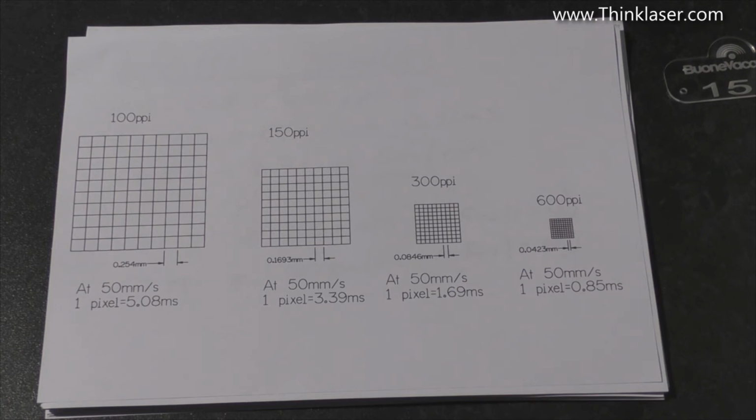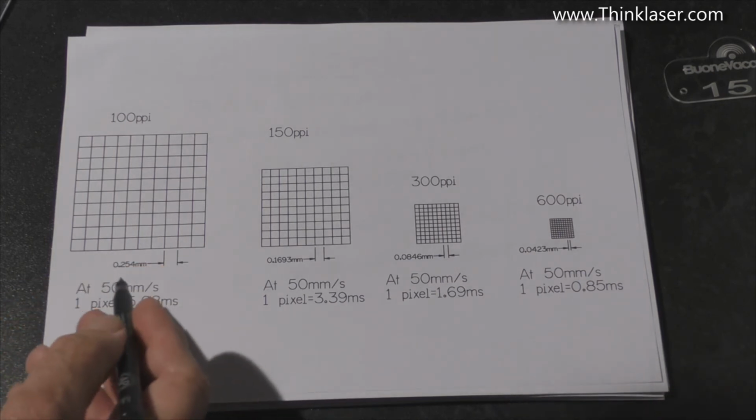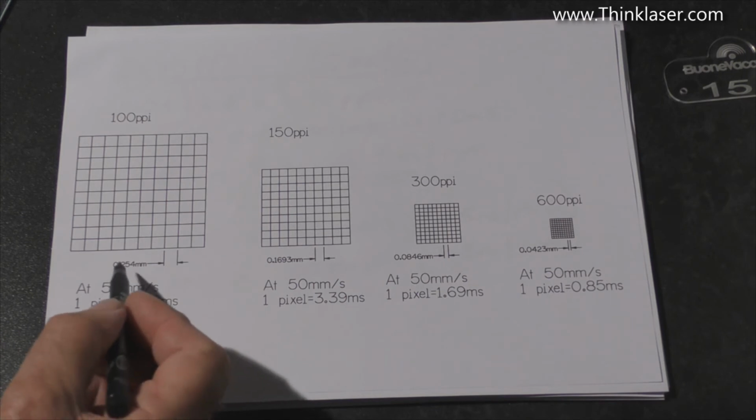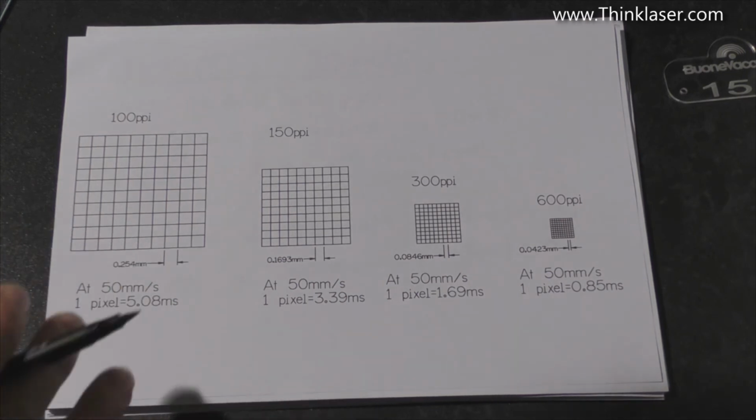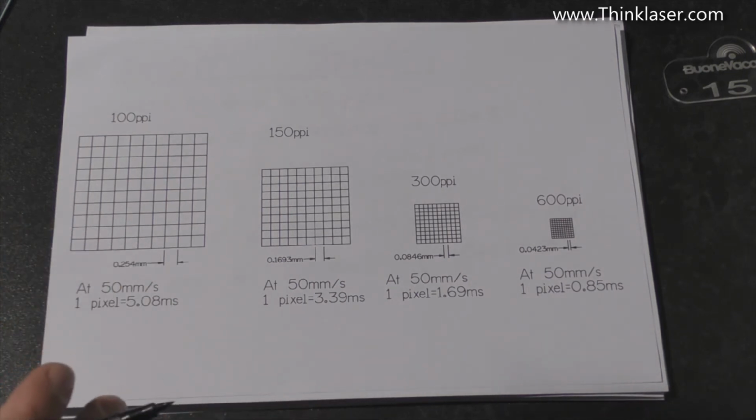Now things are starting to get quite complicated, because although I've broken this whole problem down into little individual elements like this, they can't actually exist like this in reality. A typical dot size for a 2-inch lens will be probably somewhere in the region of about 0.2 in practice. I know theoretically it should be 0.1 of a millimetre, but in practice when you start burning it you'll find it very difficult to get much less than 0.2 of a millimetre.